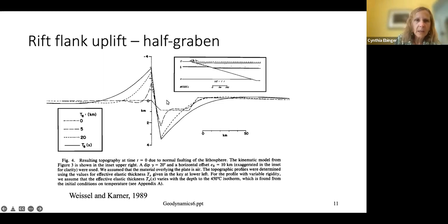Well, in the case of no strength of the lithosphere, that's this dashed line. I balance column A with column B. I look at my net uplift, and I get a basin depth of about 1 kilometer. All of the subsidence occurs in the basin, and the basin subsidence has the isostatic adjustment lift the basement a little bit. And this is what we get. We predict a 1 kilometer deep basin.